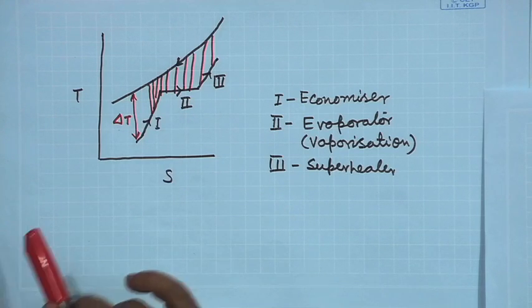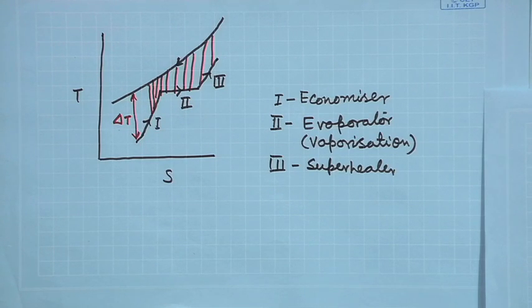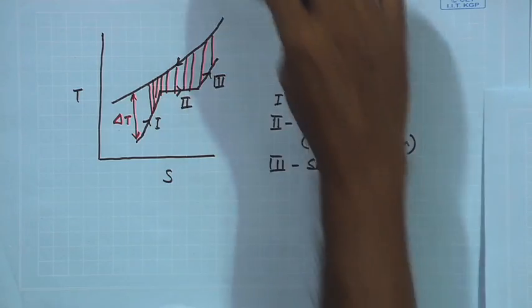The Carnot cycle has higher efficiency compared to other reversible cycles operating between the same temperature limits. So, this is the cycle modification we want to do, and that is what we are attempting through a regenerative steam power cycle.